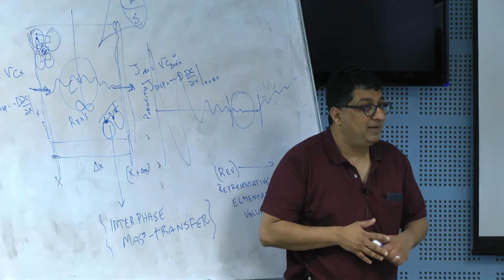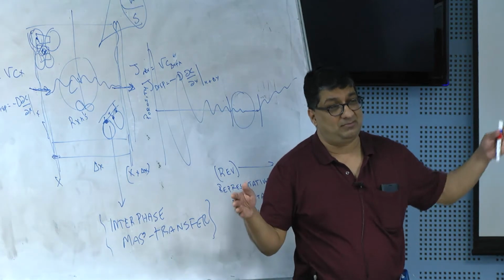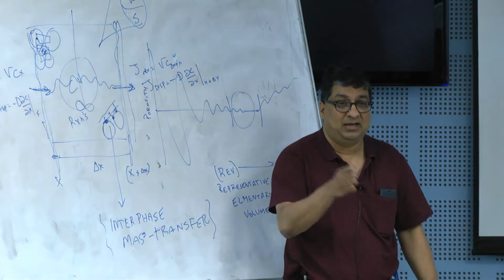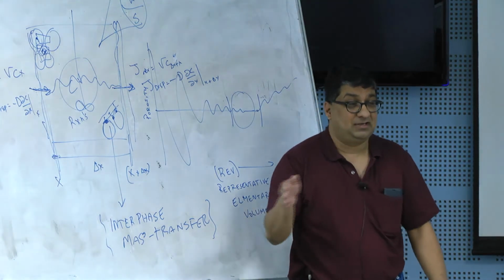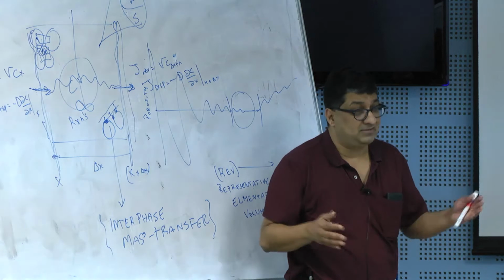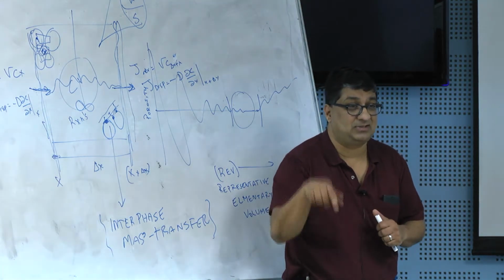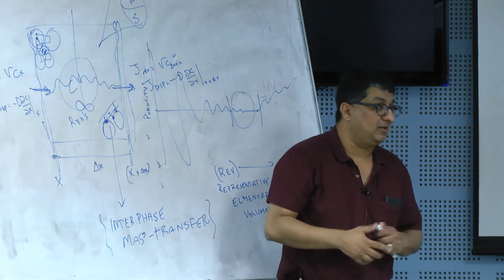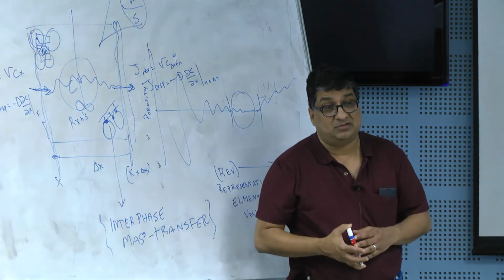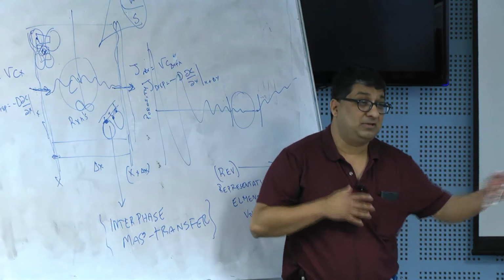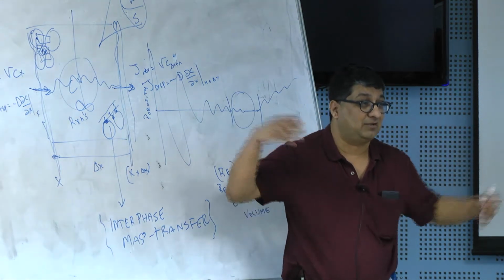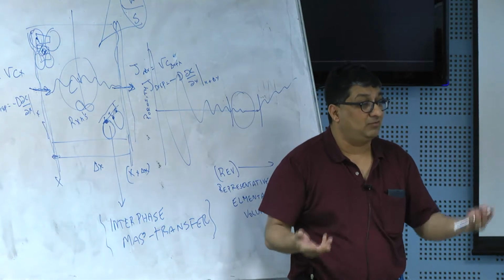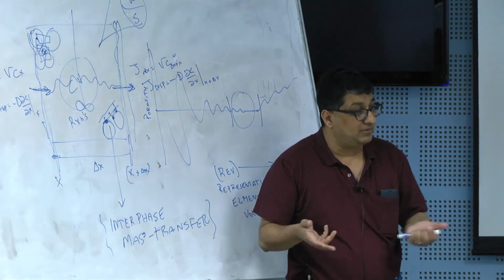Okay. If I make it too small, then I will have an infinite number of control volumes. That simulates, if I have an infinite number of CFSTRs in series, that is the same as a plug flow reactor, because the residence time is virtually 0. There is no time for it to stay, it will keep on moving. So our aquifer in some ways behaves as something in between a plug flow reactor and a CFSTR, which means there are a finite number of control volumes, each control volume mimicking a CFSTR.